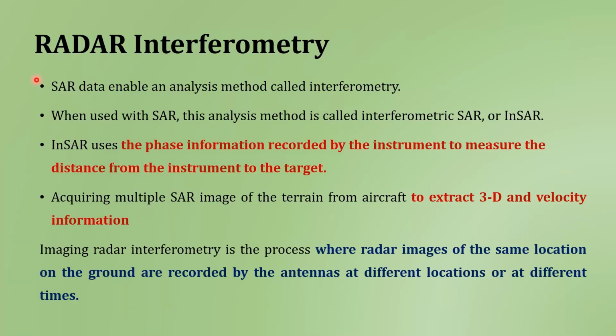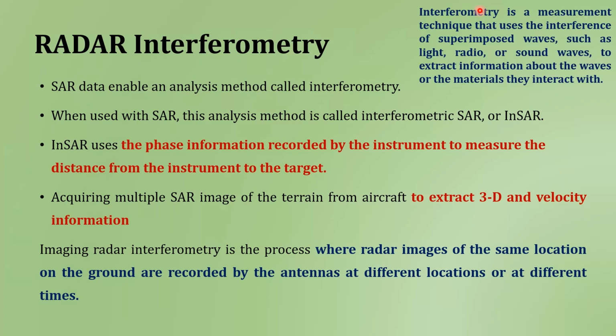Now coming to the topic radar interferometry. The SAR data enable an analysis method called interferometry. So interferometry is a measurement technique that uses the interference of superimposed waves such as light waves, radio waves or sound waves to extract information about the waves or the materials they interact with.